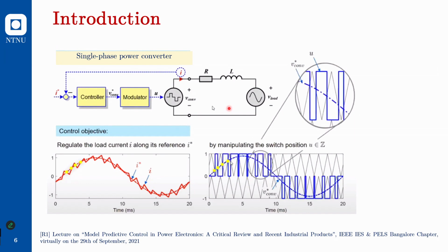The advantage is not limited to this only, because ideally you are connecting renewable energy sources at the input of the converter through a DC link. Maintaining the DC voltage balance is another issue, right? For that, you define multiple linear controller loops to maintain the DC link voltage balance, and you make these different linear controller loops interact to produce the ultimate switching logic. However, we can do all of that within a single control algorithm called the model predictive controller. So we will see how it works.